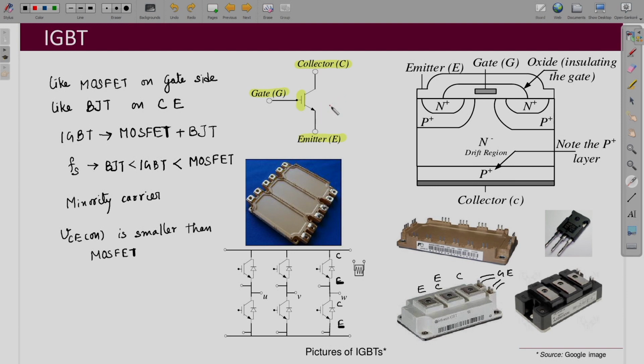So, this is something you have to do additionally, and most of the manufacturers, if they are making IGBTs with antiparallel diodes, then they will also be providing you the characteristics of the diode. And there are IGBTs also made without antiparallel diodes, although they are a little less in use, because most of the power electronic circuits that we see have the antiparallel diode requirement with the IGBT. So, that is how most of them are manufactured.